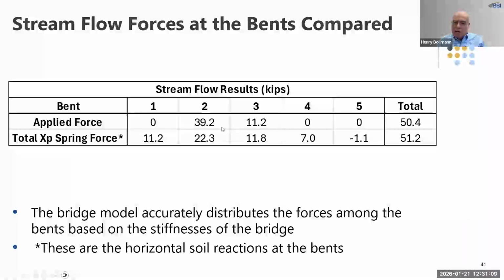Likewise here, so in other words, some of this went here to the end bend because it's stiff. All that's there is bearing pads. There's no, very stiff there. Some of it went here, and from this load, some went here and some went over here. And since it's a continuous superstructure, on the end, we get a minor uplifting force.